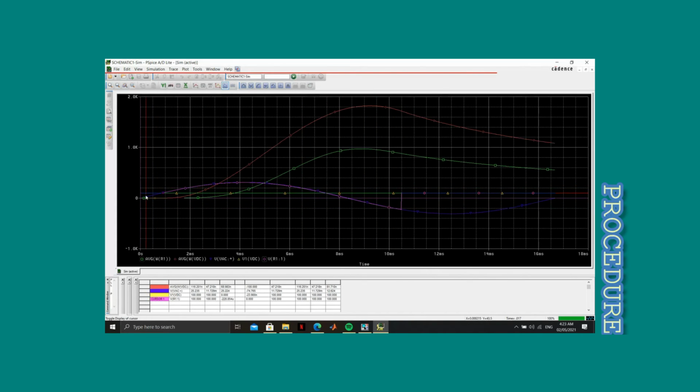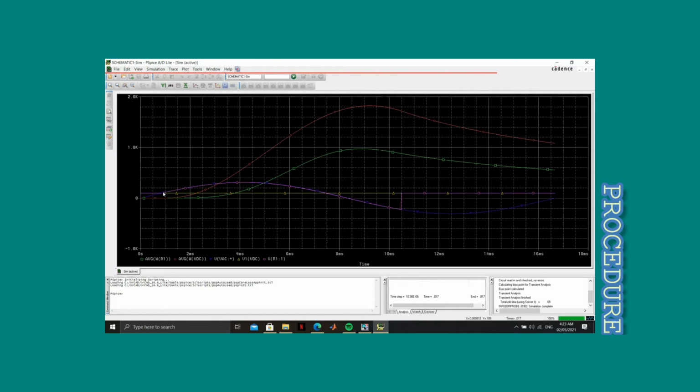To add, once the blue waveform, which is the AC voltage, and the yellow waveform, which is the DC voltage, intersect, this means that our diode starts to conduct, which means that there would be two voltage sources providing power to the circuit, which is why there would be two build-ups for the waveform across the average power of the DC source and average power across the resistor.